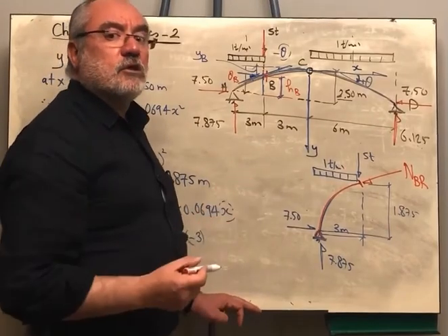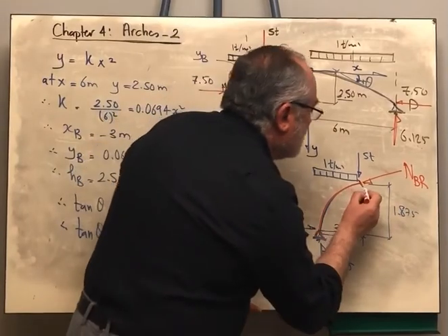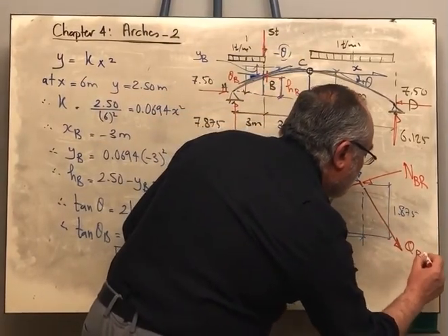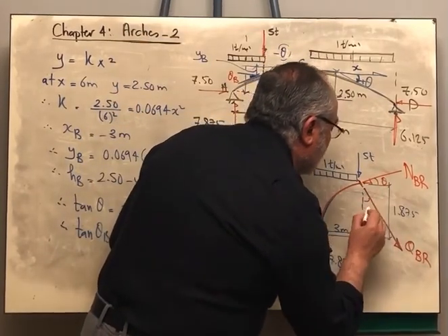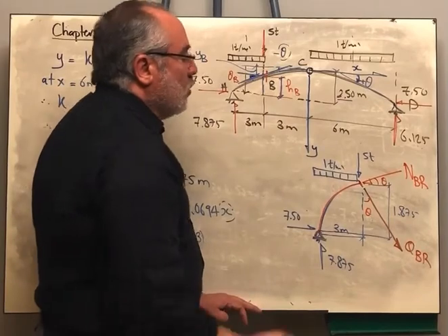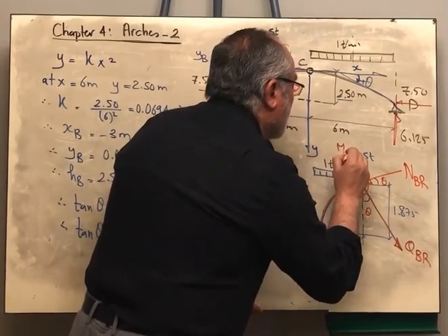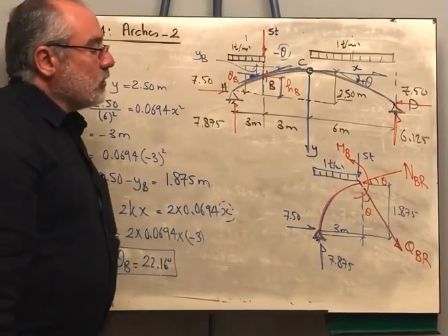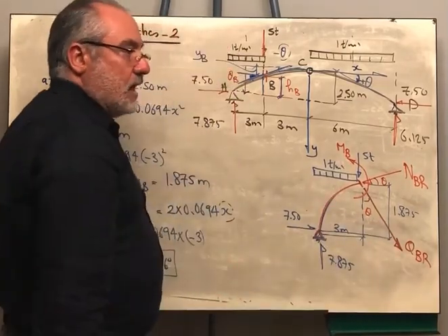Okay, we took the left hand side of the problem, but the cut section is on my right. What will be the positive direction of the shear on my right hand side? Downward. So this would be the direction of the positive shear. If this angle is theta, then this angle is theta. What else is missing? The bending moment. We are assuming the bending moment to be positive, so the tail of the arrow is under the datum. Now this is a complete free body diagram.